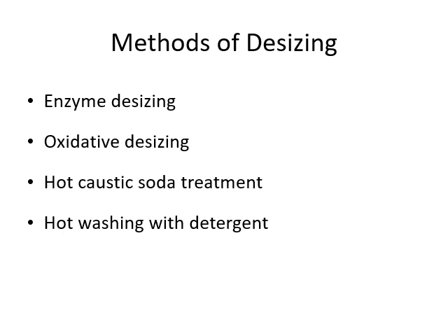Then hot washing with a detergent. Many sizes are sometimes water soluble. These are the modified starches. So they can be removed either with very warm water or cold water, as we discussed previously. Only with a detergent, to get better penetration into the fabric, hot washing is carried out. So there will be a better removal of size materials.